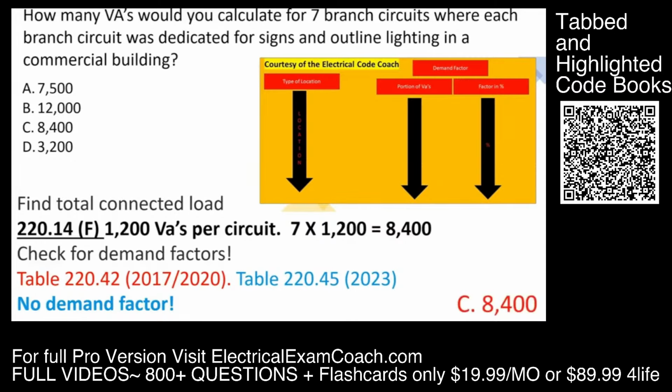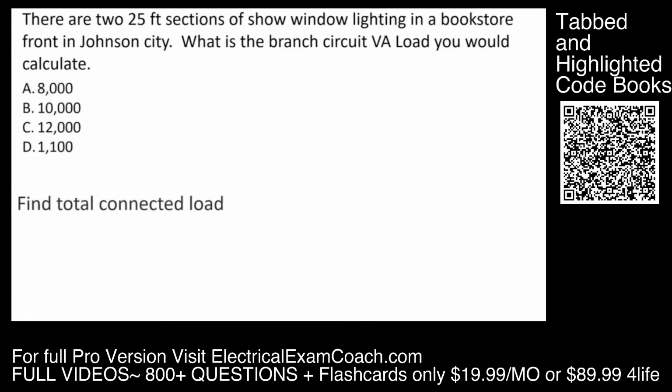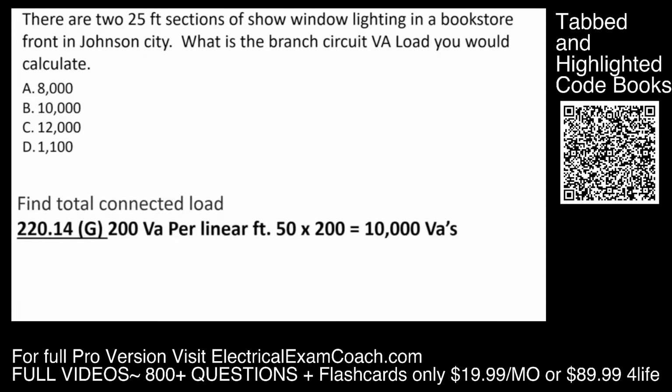Great job. There are 2 25-foot sections of show window lighting in a bookstore front in Johnson City. What is the branch circuit VA load that you would calculate? Step 1, we're going to find our total connected load. For this, we're going to head to 220.14(G). It's going to let us know that it's 200 VA per linear foot. We take our 50 feet multiplied by 200 VAs each. That's going to give us a starting connected load of 10,000 VAs.